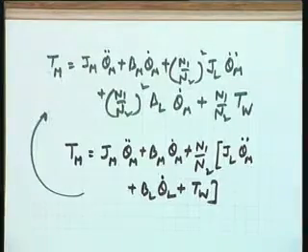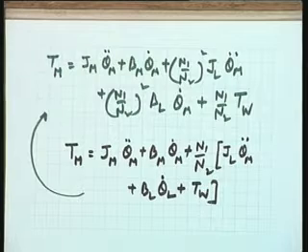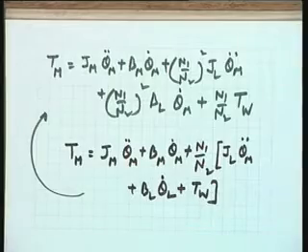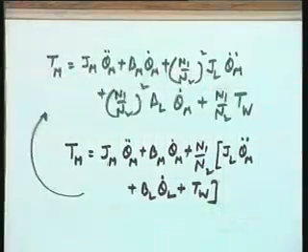You will see in this equation, theta L dot and theta L have been replaced in terms of theta M. You know the expression, theta L by theta M is equal to theta L dot by theta M dot is equal to the gear ratio N1 by N2.